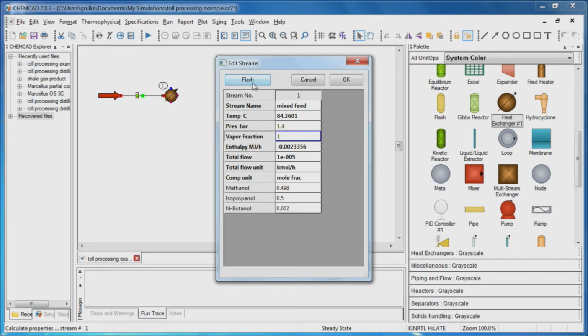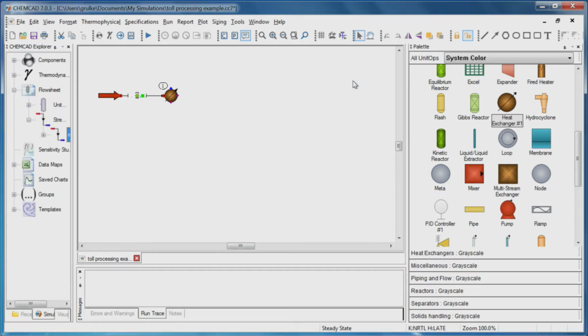Okay, so this is going to be a very useful tool. We'll have it several times today when we're talking about this problem. So let me go back and reset these conditions, if I can. Take out the vapor fraction, put in the actual temperature we expect. Okay, we'll flash it. Okay, vapor fraction 0, it's all liquid feed, that's great.